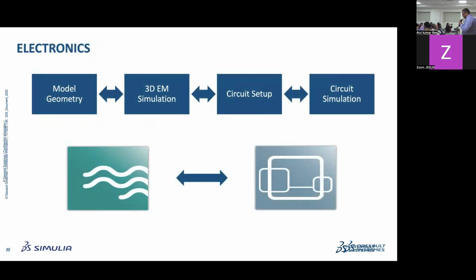So firstly, conducted emission. Because you said the term itself is a little new, which is good. Conducted emission means that let us assume you have a lot of devices connected to the same power supply. If there is a switching behavior in one of the devices, the chances are that there might be a high frequency spike that goes back into the power supply.